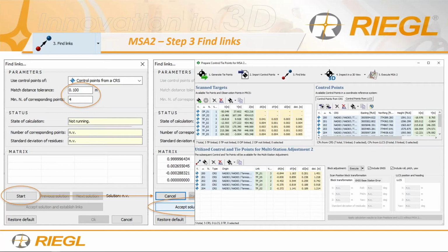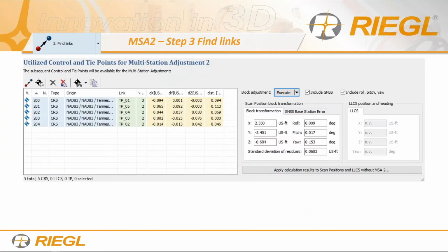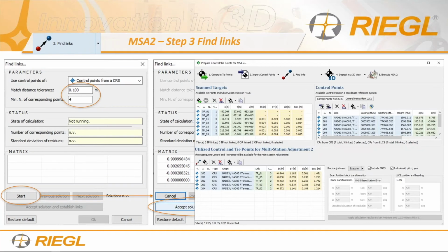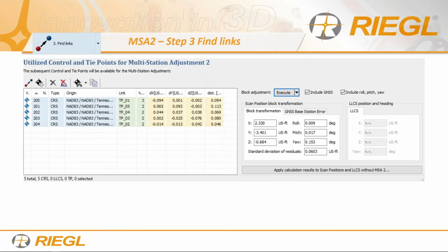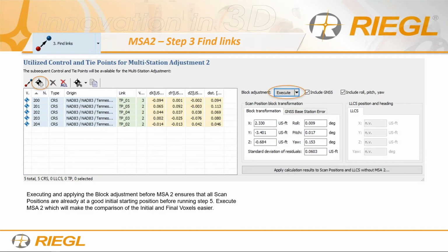Okay. And then on the bottom is the link. Now, there's going to be times where, on this project I have 5 survey controls, so there's only 5 links here. But there's going to be times where you don't find all the links. Well, that box I just highlighted in a circle will be green. Okay, that will tell you that hey, I didn't find another control. Do you want me to force the other one in there? Or make use of it, rather. And of course, you want to go ahead and hit yes. But it'll be green if there's any available that it didn't find.